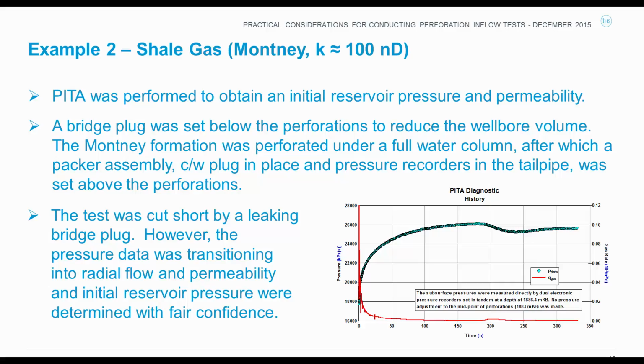When the plug with recorders was about to be retrieved, when the operations on the well resumed at the end of the build-up test, there was no pressure at the wellhead, and this is a slightly overpressured formation, so if the top plug was leaking, we would see some pressure at the wellhead. So that's what led us to believe that it's the bottom plug that was leaking. Let's switch to the software and look at this example.